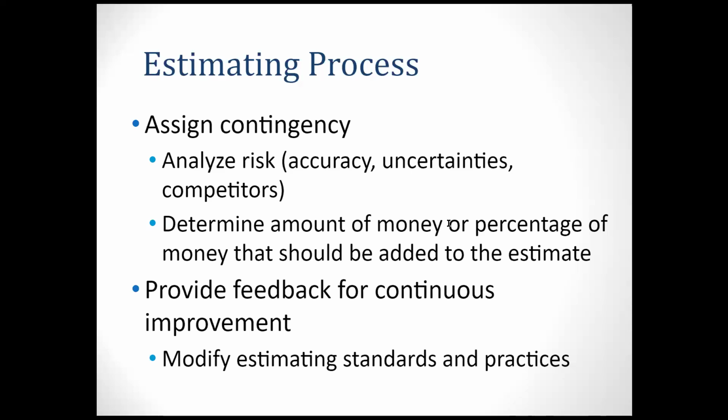And accuracy. The accuracy comes from two parts. Either the owner-provided information is accurate, or your team may have some mistakes, right? Uncertainty is that the geo conditions may change, because the geo report provided by the owner may have some issue or ignore something, but that will impact you, right? And also the traffic condition. For example, say the DOT says they're going to reconstruct this roadway in the next 2 months, and your scheduled project start time is just within that period, right? That will totally impact you, right? Or cold weather happens, and you cannot do the construction during that time. Those are all risks, right?